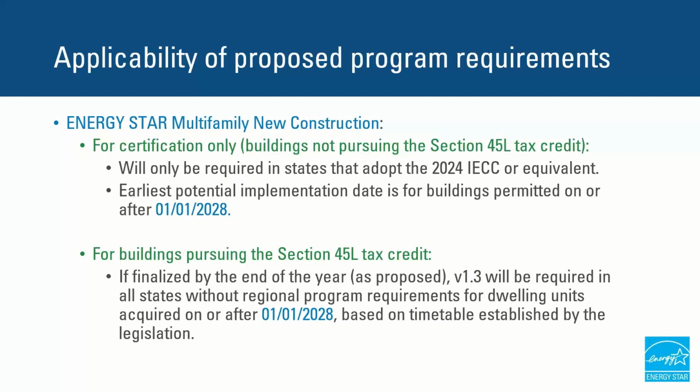Separate from the Energy Star reference design, which defines that ERI target, we have our mandatory requirements that every home has to meet in order to be certified, covering the thermal enclosure, the HVAC system, the ventilation system, etc. And so for those mandatory requirements, we have 2 tracks. We have what we call track A, we have track B. Track A is based on HVAC grading.